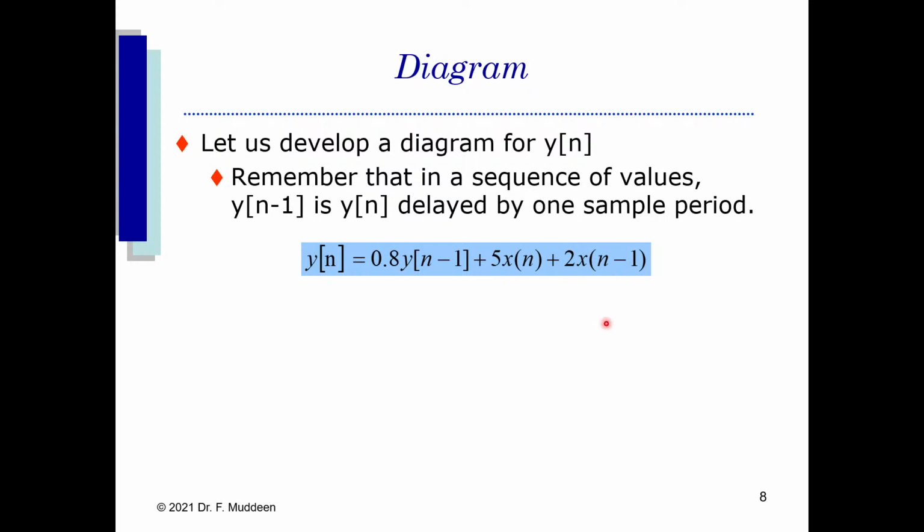So let's use the input-output difference equation here to actually develop a block diagram that will map y of n, being our outputs, to x of n, being our inputs. In drawing any block diagram in particular, we always put the inputs on the left and the outputs on the right. So we want to start with our input, x of n, on the left. And then we see here that we have an x of n minus 1, being that this is a delay. So we cascade those downwards to represent the delay levels. This horizontal level here will be at x of n or y of n. This next horizontal level here will be at x of n minus 1 and y of n minus 1 accordingly. And if we had one more going underneath, it would be at x of n minus 2 and y of n minus 2.